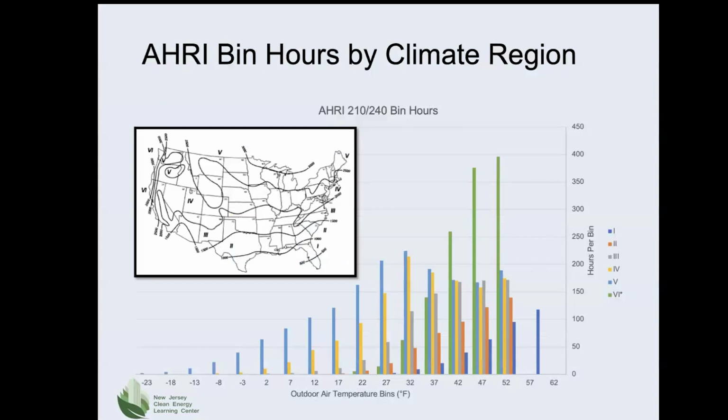This slide is included in part 3, selection and sizing, rather than part 2, load calculation, because it underscores the importance of turn down ratio. Climate zone 4 here on the East Coast is represented by this gold colored vertical line in the graph. On the right-hand side, you have hours of the year, the number of hours that it operates at a certain load level. And then underneath, it's correlated, on the horizontal axis here, to outside air temperature.